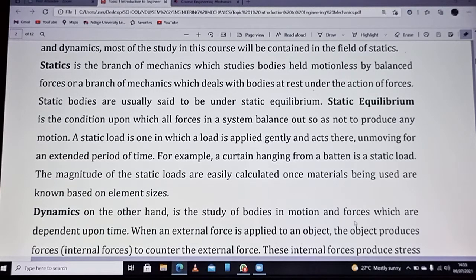What else could be an example of static forces? Even when we talk about the walls, the weight of the wall onto the beam, or the weight of the column onto the foundation, all those are considered to be static forces. These forces will never leave their position unless there is failure. So any fixture or installation that you have in the house, a fridge that is placed in a given corner, is a static force. It only leaves that point to another point if you, the user of the house, choose to shift it to another place.